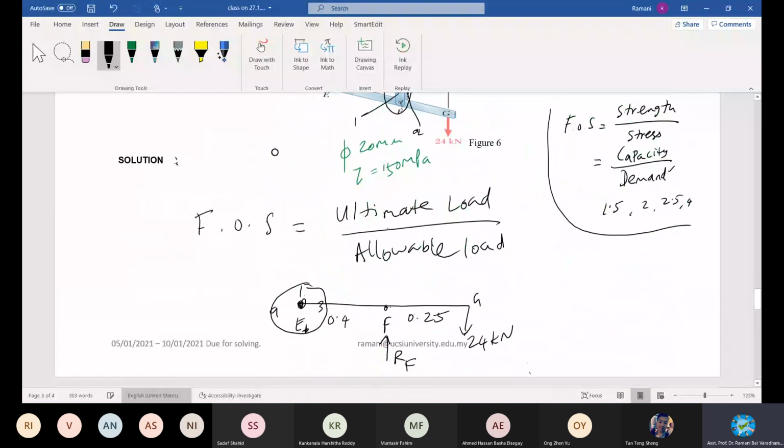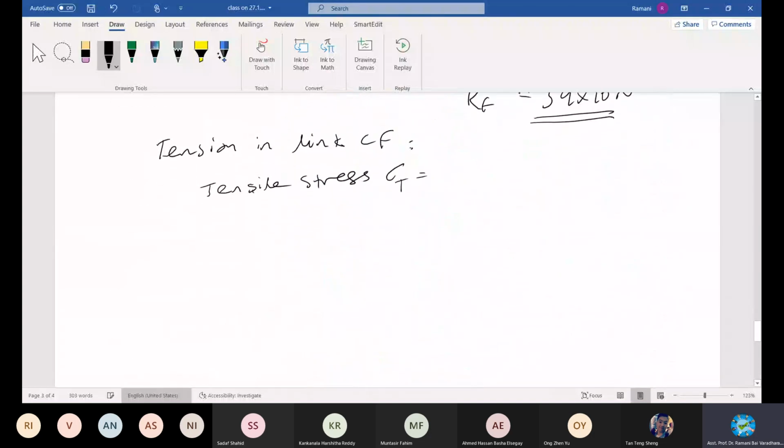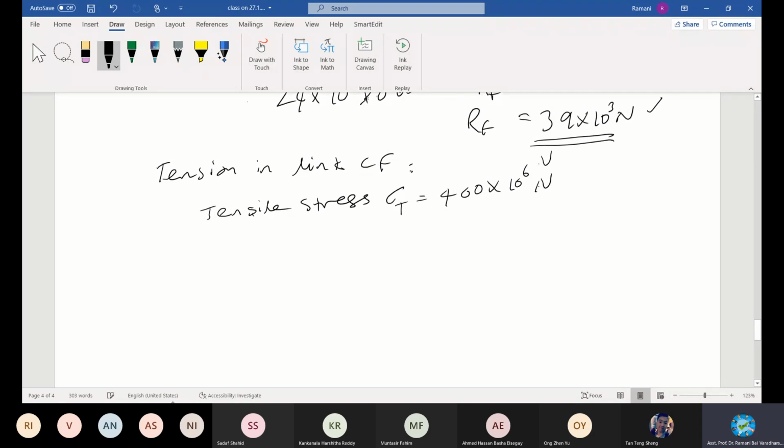Let it be in the same unit. I changed 400 megapascals to pascals. It is easy for us, because later I end up with newtons, because I already have newtons here. So this is the value given to you as megapascals, and then we need to find the load, right? Write the formula for this. This one is tensile force, right?